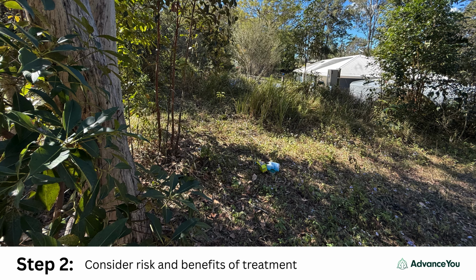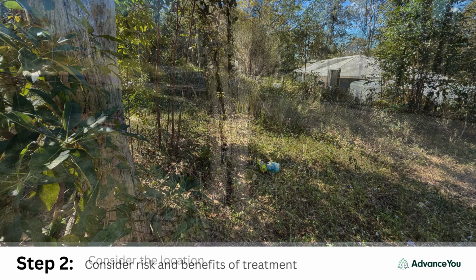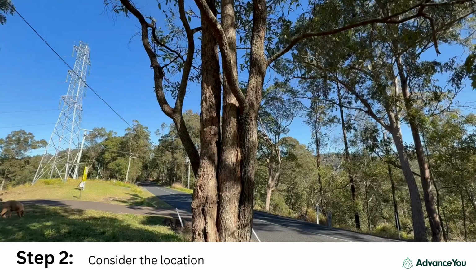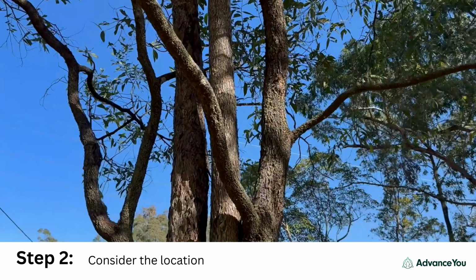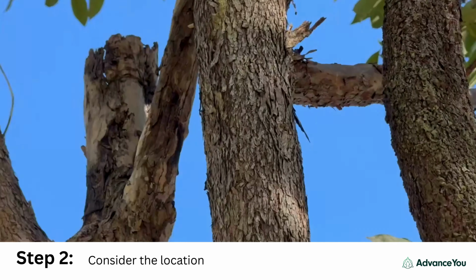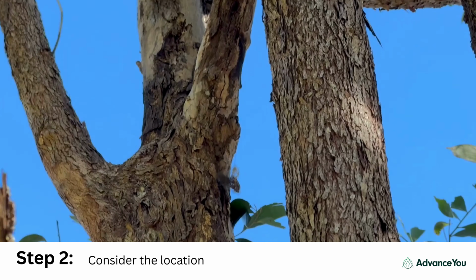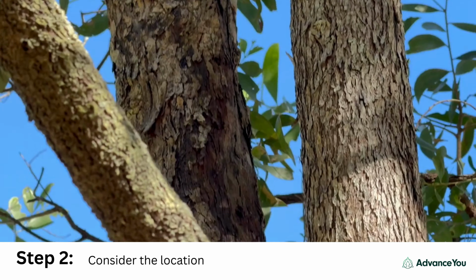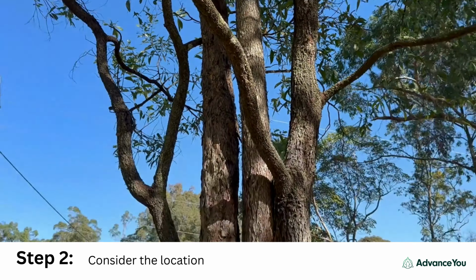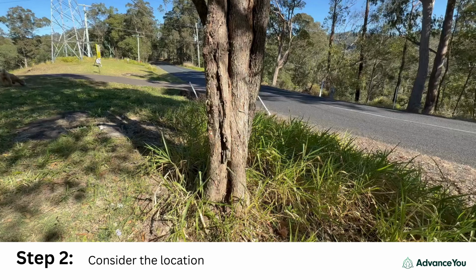During your site inspection or test drilling methodology, you may confirm the presence of a subterranean termite nesting in or around a tree. You then need to ask yourself, is this nest posing a risk to the building and should I treat it? We don't want to be treating subterranean termite nests that aren't posing a risk to the building, either based on their location or the species of termite.